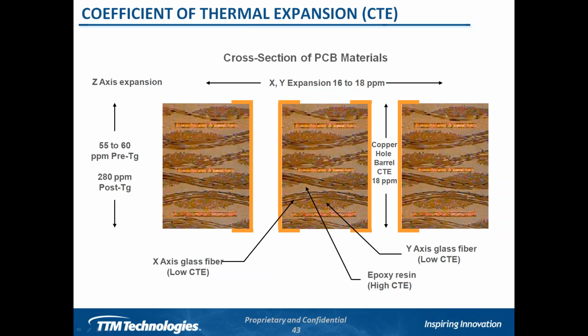So with assembly temperatures today in the 260 C range, we are going to be past TG of the material, but the question is, can we stay above it for as little time as possible before we start to damage the material set? So CTE in relation to TG, in relation to the actual construction of the circuit board, becomes very critical for a material set.